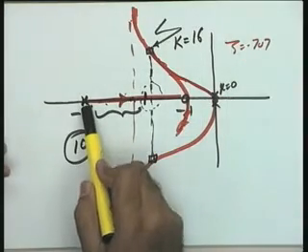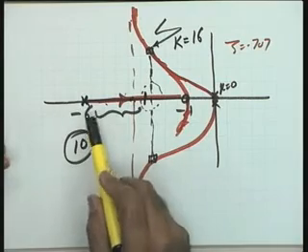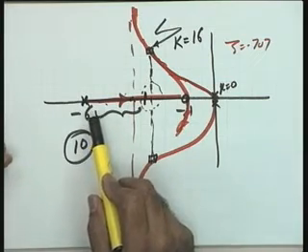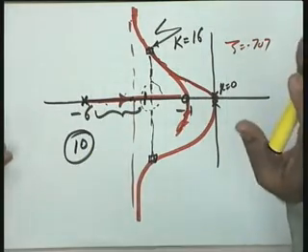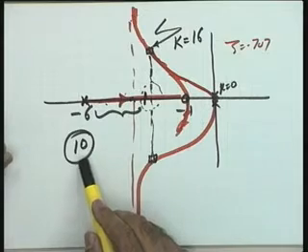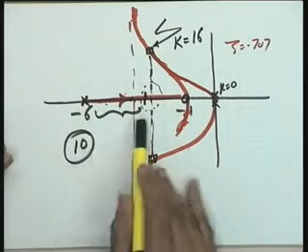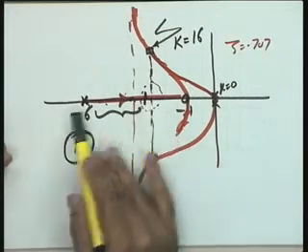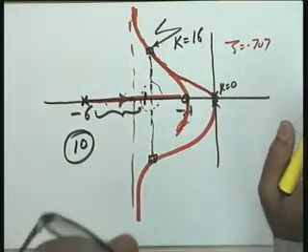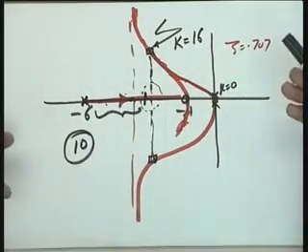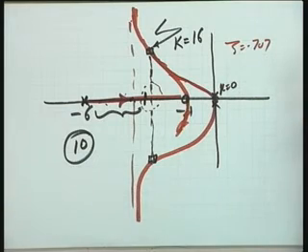You see, after all, it is a high frequency attenuator. This particular pole which you are placing at -6 is going to attenuate the high frequencies. A reasonably good attenuation will come if a value of 10 is there as the ratio between the 0 and the pole. This is again a guideline. However, this may contradict with the angle requirements, and you have to suitably take care of this point as well. So you see that as far as the design procedure is concerned, only certain guidelines have been given to you and no quantitative method can be given in this particular case.